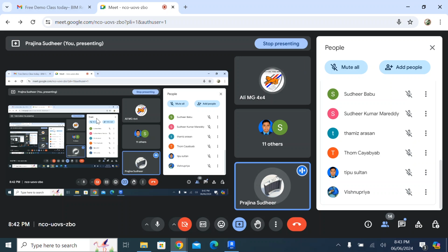But in Revit we will learn how we work as a team. When we do the training, only one person is doing it, right? But normally in offices it is not like that. Many people will be involved in the project, and we create a federated model. In Revit itself we have the options of worksharing and worksets. We will discuss that. You are doing that in the local space, but for BIM Collaborate Pro the scope of that space is worldwide. That is the only difference.